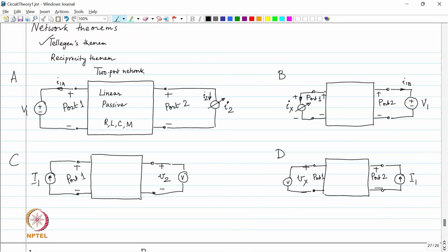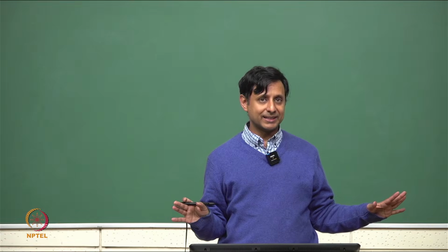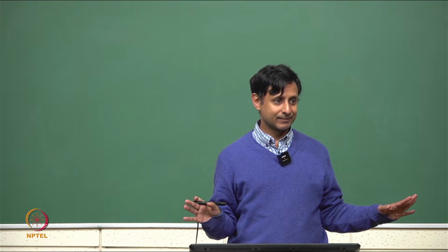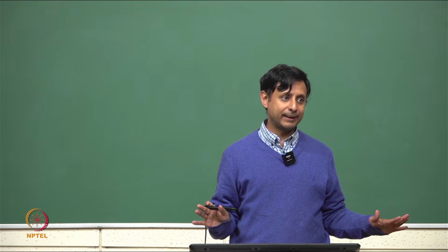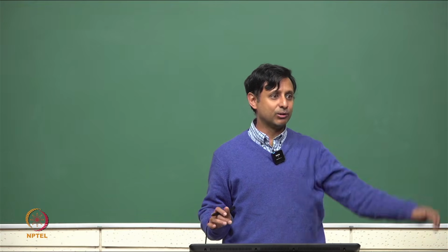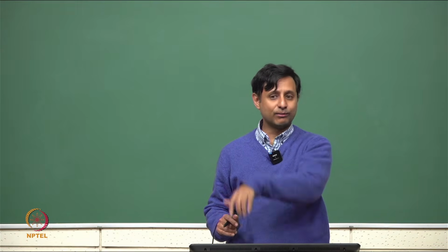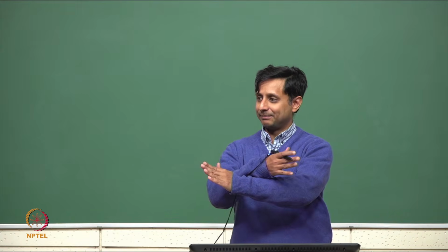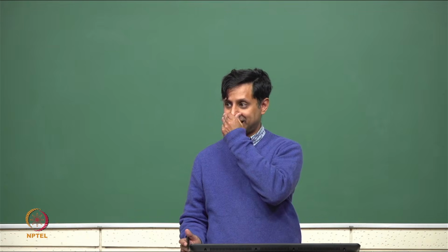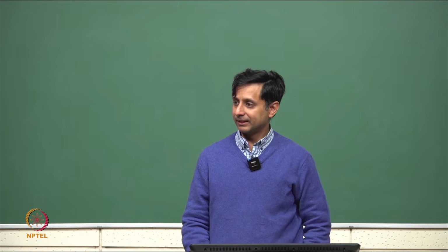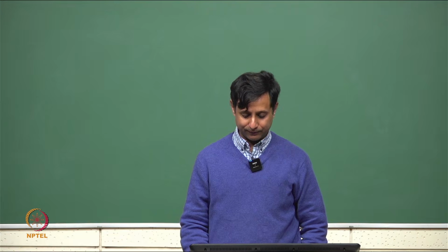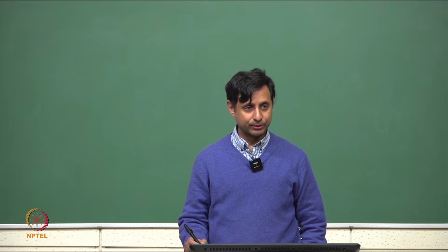There is a physical component over there called a voltmeter. The topology of the circuit remains exactly the same in both cases. So, you apply Tellegen's theorem, list out all voltages, all currents here, list out all voltages, all currents here, and then mix them up, do the mixed dot product twice. That will automatically give you Vx is equal to V2.